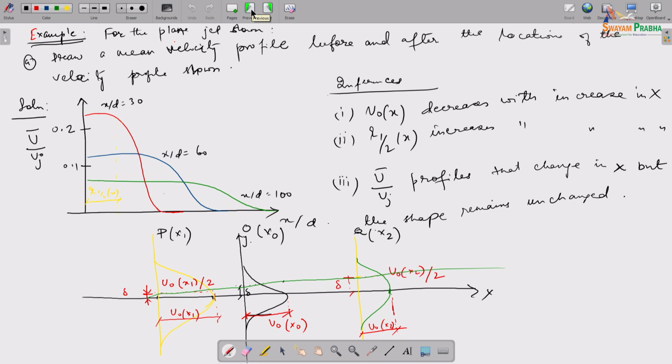This is a turbulent flow, but it seems to have similarities with the boundary layer. In a boundary layer you also have a velocity which is dominant in the x direction, and all the differences are concentrated in the y direction, and the thickness of the boundary layer. The thickness is the layer till which the viscosity is confined, and beyond that there is no boundary layer.